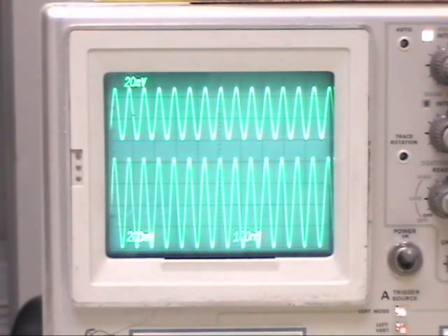There's a rule of thumb you can use. Well, it's not rough, it's exact, for certain values of dB. When we're talking about voltage, every 6 dB causes a doubling of voltage, or if you're attenuating, it makes it go to 1/2. So 6 dB is times 2 or times 0.5, depending on whether you're amplifying or attenuating.